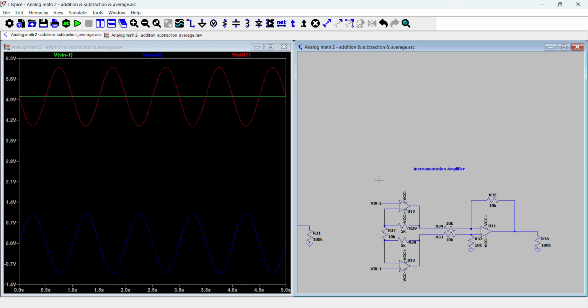For example, let's say a radio wave hits an antenna. It's not going to be able to drive a large current. So therefore, those sensors would have a really large output impedance. It's essentially like adding a resistor here that has a really large value.